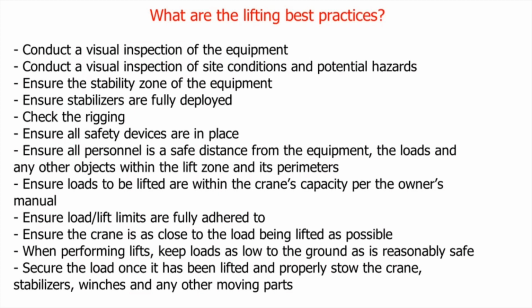Ensure all personnel are a safe distance from the equipment, the loads and any other objects within the lift zone and its perimeters. Ensure loads to be lifted are within the crane's capacity per the owner's manual. Ensure load lift limits are fully adhered to. Ensure the crane is as close to the load being lifted as possible. When performing lifts, keep loads as low to the ground as is reasonably safe. Secure load once it has been lifted and properly stow the crane, stabilizers, winches and any other moving parts.